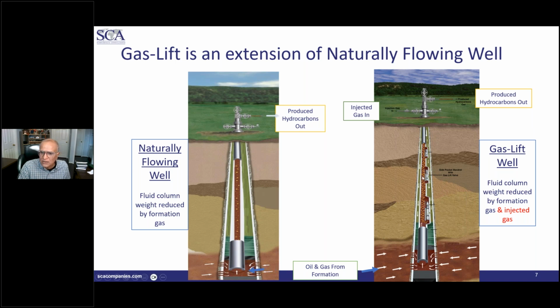And so the main equipment, if you will, in the gas lift, as far as inside the wellbore is concerned, is what is called a mandrel, which holds the gas lift valve. And then the location of this mandrel and gas lift valve is important because the deeper you go, the longer column of the fluid gets lightened. But again, these are all discussions that are carried out in detail with the hydraulics related calculations in the class setting.